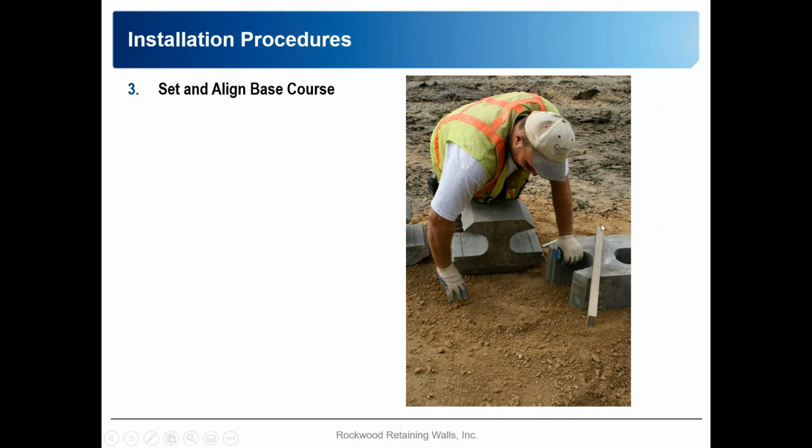Some contractors will put in additional batter or taper, making the tail slightly lower than the face. That's not wrong. However, if a contractor is going to add additional batter or tilt in the base of the block, it's important that they maintain consistency. So if this unit is dropping 3/16 of an inch, the unit next to it and all of the units next to it maintain a 3/16 of an inch setback or batter.